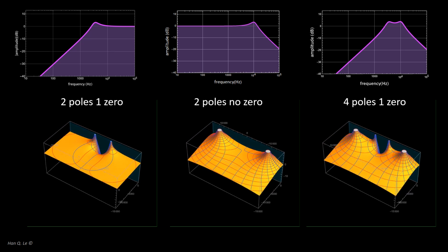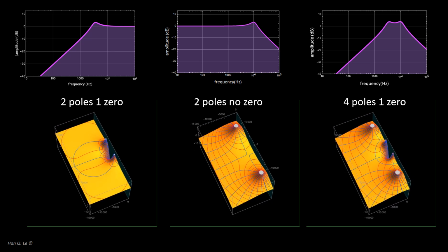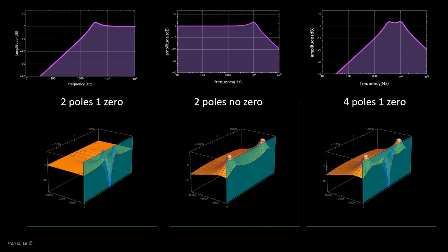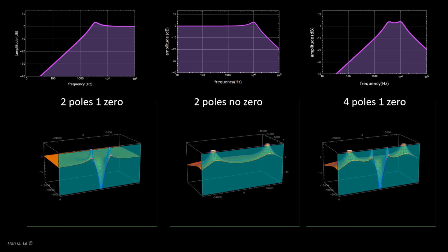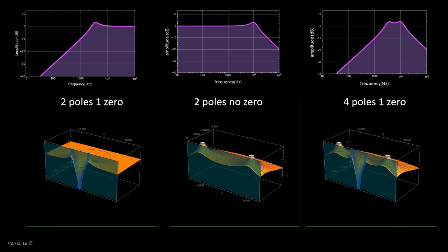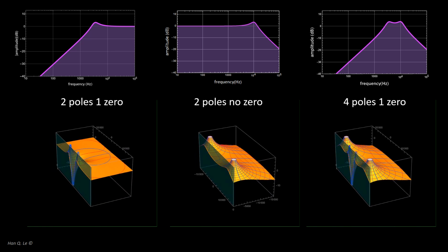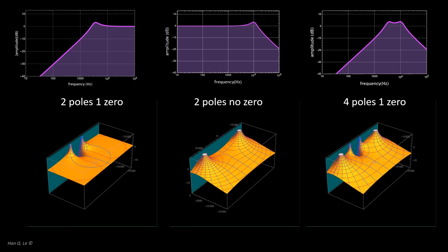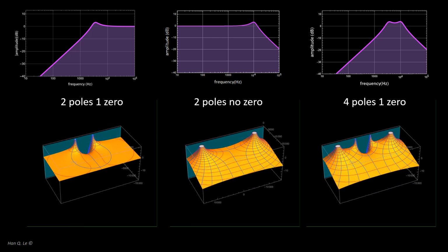The locations of the poles, which are the same as the roots in the root diagram, show the intended design of this lab, which is to demonstrate underdamped oscillatory behaviors, also known as resonance behaviors. This is different from purely passive RC filters, without inductors, which cannot have resonance behaviors.